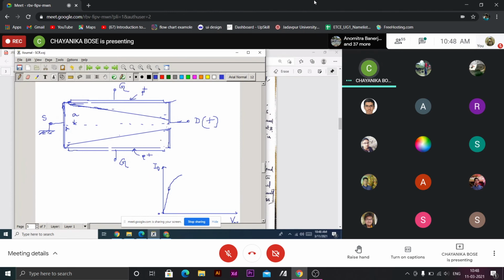So in this depletion region, there are positively charged donors. I am only showing the positive charges. The same on this side. And since P plus is a heavily doped, one-sided junction, we are not considering extension of the depletion region within the P region, but there must be an equal number of negative charges in this P plus region. So the direction of the field in this depletion region is this one. The concentration of donors is the same here, but the width is larger.